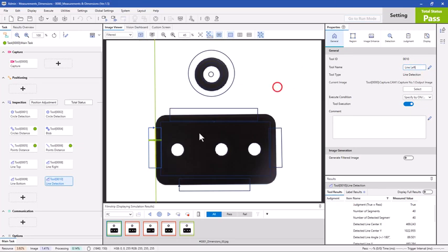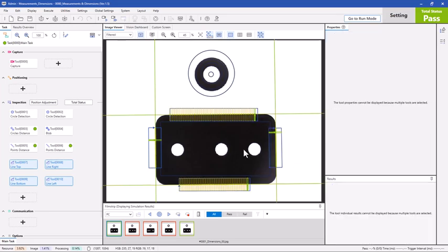All right, and then we have our four lines detected on all four sides, and we could do other measurements on them. What I'll do now is I'll show an example of getting the distance between a circle center and a line. So we'll calculate how far this circular part up here is from the top line of this target here.